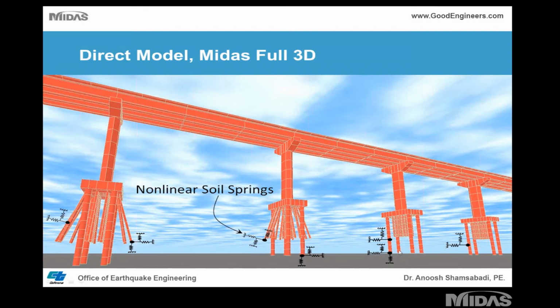But all these nodes, you can see all these lines, they all have 3 component springs attached to them in both the longitudinal and the transverse direction, as well as the vertical direction, which is called PY, and this is called TZ, and at the tip, we call them QZ curves. So they are all incorporated in the model, including the massive pile cap and the superstructure.